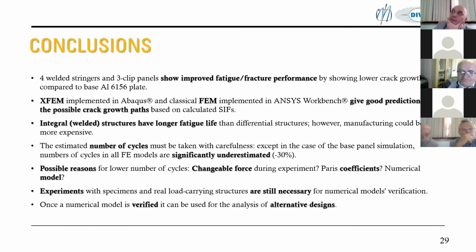And to conclude this, if you talk about these clip panels and the stringer panels, 4 welded stringer panels and 3 clip panels show improved fatigue fracture performance compared to base metal. So we saw that the base metal plate was around 200,000 cycles, but in a case when we have 3 clips or 4 welded stringers, we have more than 100% improvement compared to this.